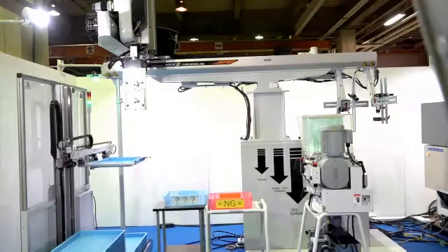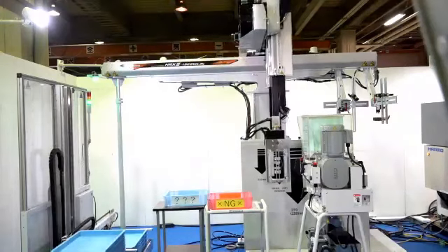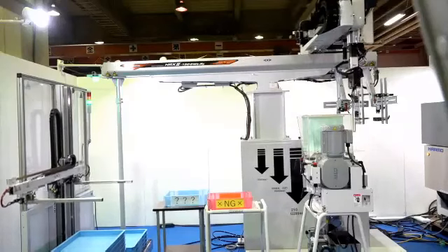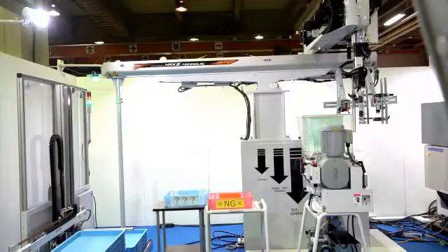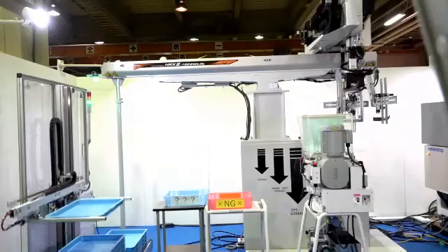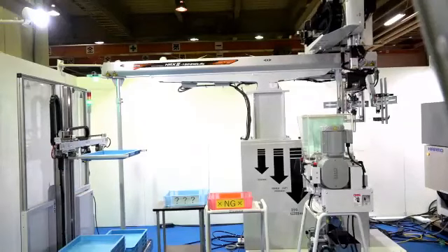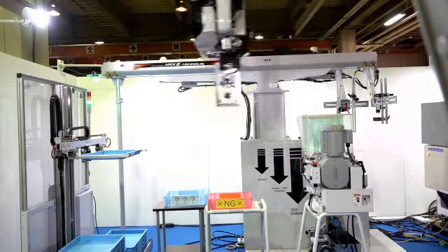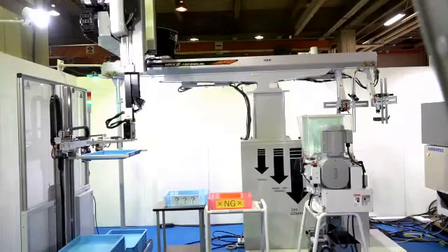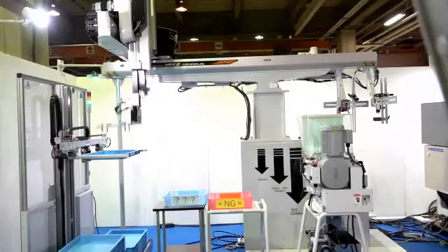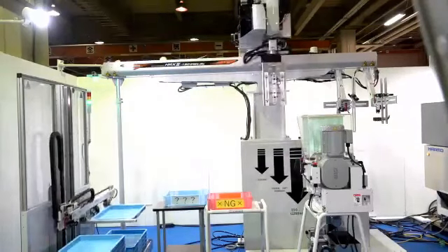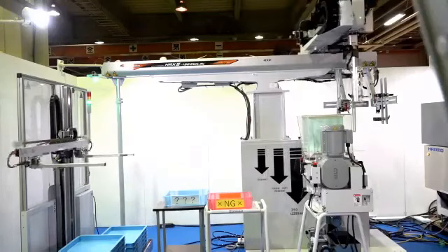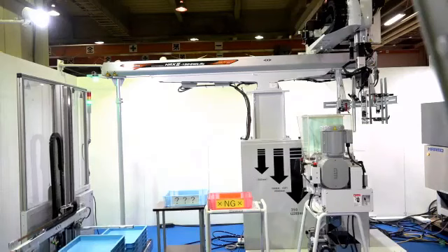If the machine is stopped completely with the error, to restart the whole equipment takes a lot of time and energy. It is possible to solve the problems with Total Link without stopping the operation. Production defects can be separated to two places, inspection place and defect place. Also, you can set how many times the robot releases the product to each place. Of course, if the error isn't canceled within decided times, the robot stops its operation with an alarm.